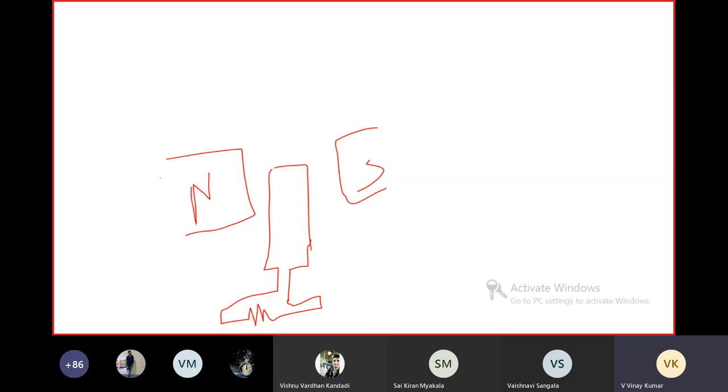No EMF is induced until there is time variation between the magnetic field and the conductor. So we need to produce time variation between the magnetic field and the conductor. What are the essential requirements to produce EMF? First, we require a magnetic field; second, a conductor; and we need time variation between the conductor and the magnetic field.